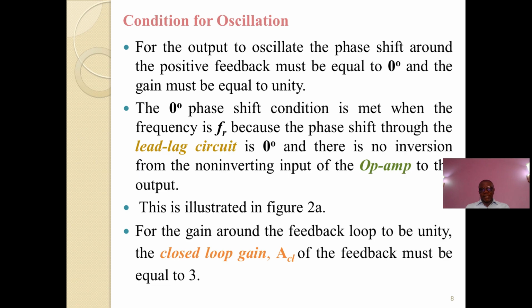So that is why in that response plot, it is important to note the position of Fr, that at that point, which mathematically we can say is the point of reflection, the lead circuit and the lag circuit have 0 degree phase shift.